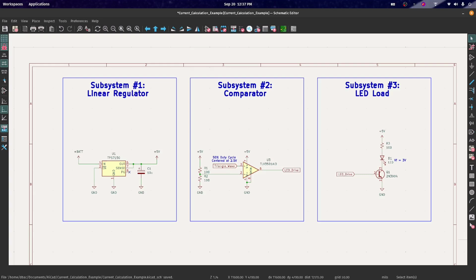Imagine if you made a project that monitors the temperature, but you needed to replace the batteries every single day. The project would be useless. You'd ideally want to keep the project running for weeks or months at a time with no intervention, not just hours. Sizing the battery should be one of the steps during the design process, not something left to after the design is completed. That means the desired battery life needs to be one of the design constraints, the same way input voltage and size are.